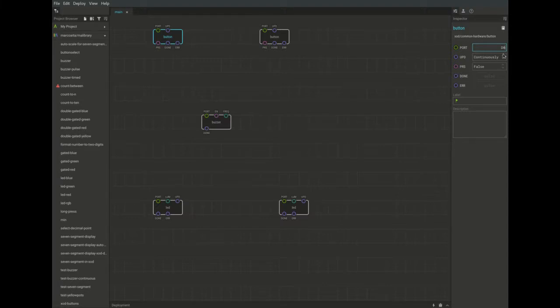If you look at the integrated shield, you would notice that both buttons and the LEDs have attached to them a number, and that number actually is a number and a letter. That would be a D or an A. The A refers to analog ports and D to digital. So in the case of the buttons, you need to have ports D2 and D3. In the case of the LEDs, you need to have 13 and 12, I think.